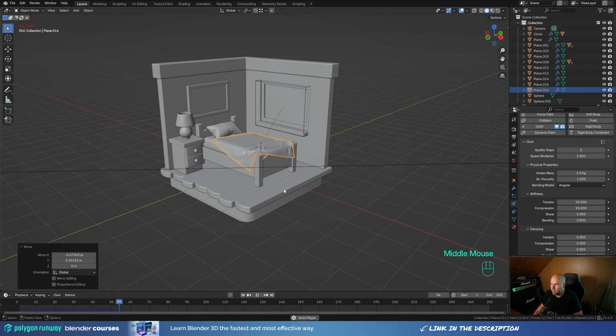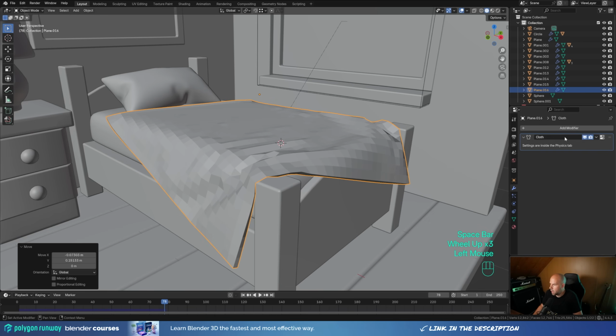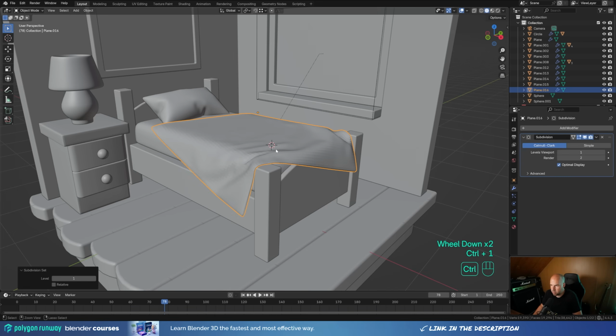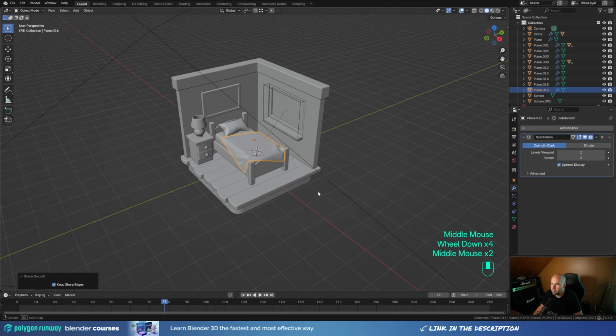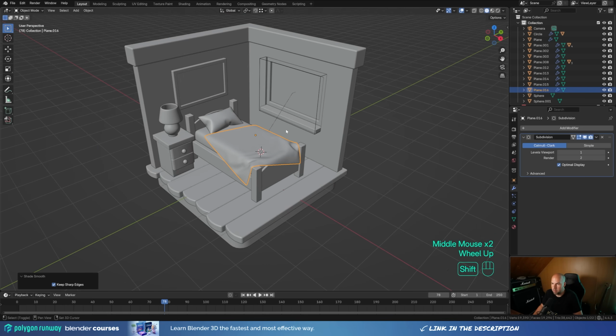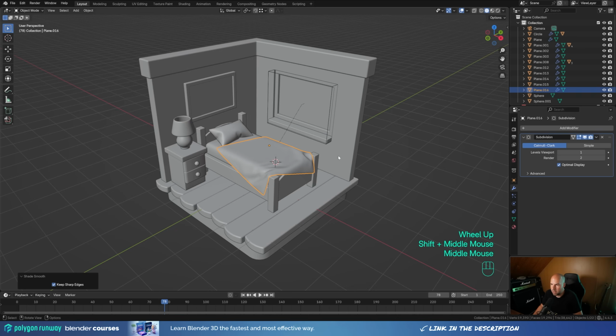This looks fine. So the moment I like it, I just pause the animation and go to the modifiers and apply this again, and press Ctrl 1 and add that subdivision surface modifier, right click and shade smooth. And here's our nice blanket, and this is basically the bedroom illustration modeled, and we can add some lighting and add some simple materials. Let's go and set up that.